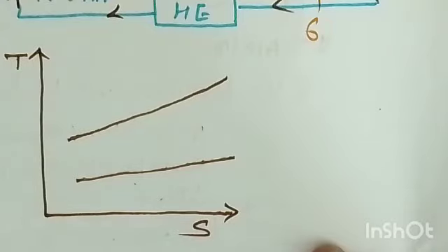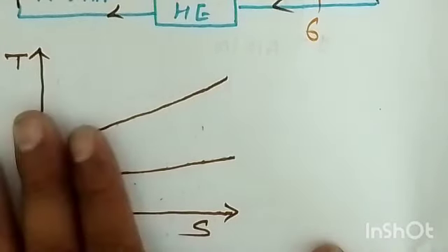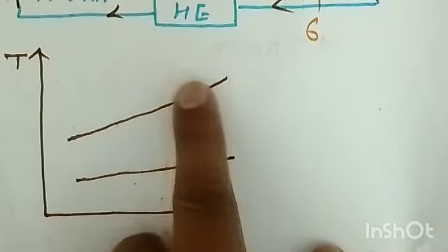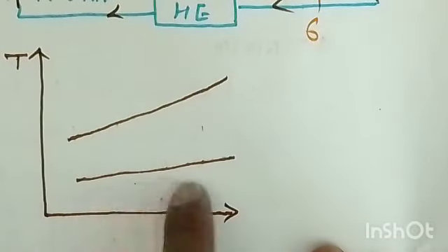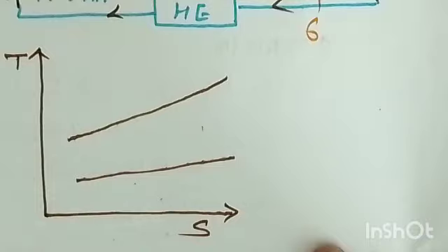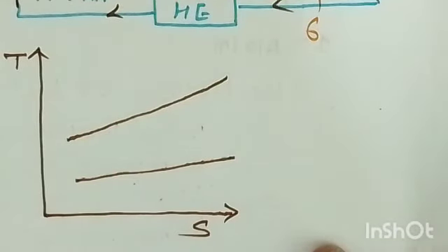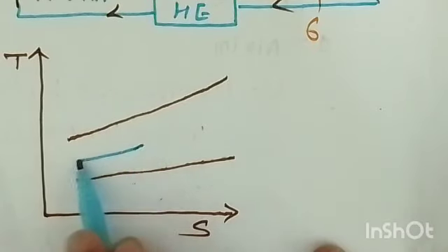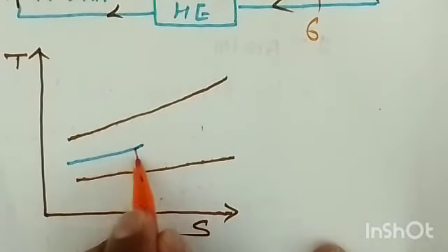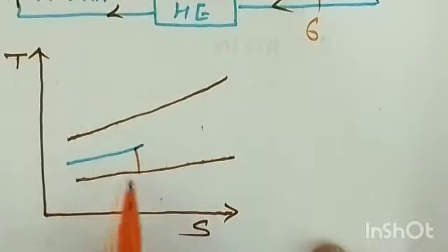Now, stages. Where are we doing the stages? In compression. So this side you have a compressor and this is the turbine. Here is the combustion chamber and this is the heat rejection. You know that basics we have already discussed. So let's say we are splitting this compression area into 2 stages, so that you can arrange low pressure and high pressure compression. So first you can say 1 to 2, that is reversible. This is the isentropic compression.